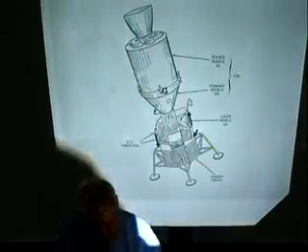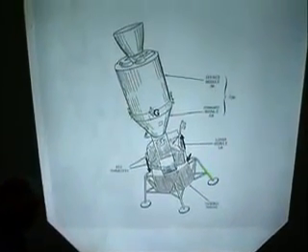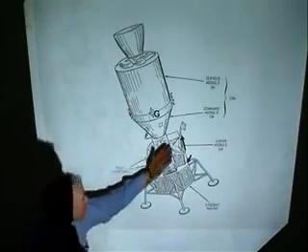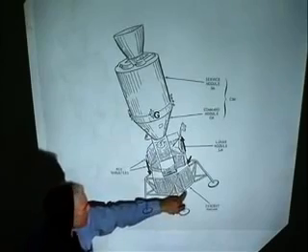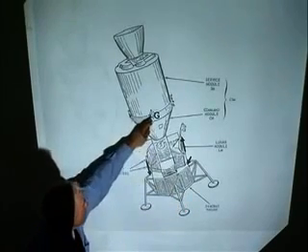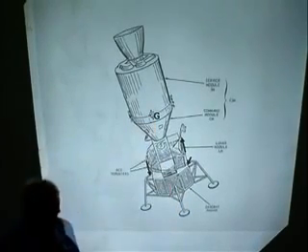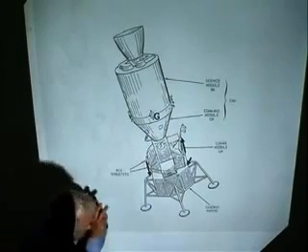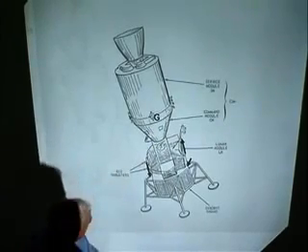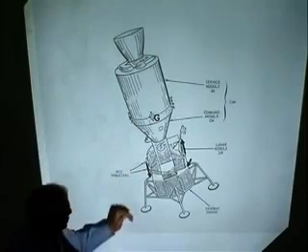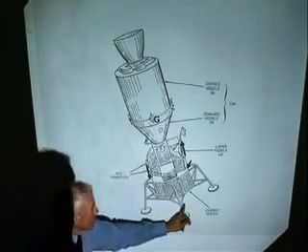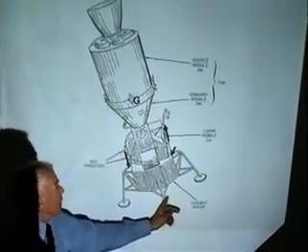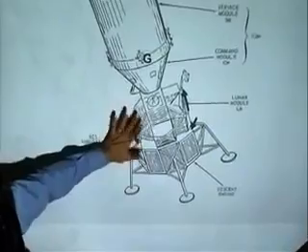Okay, so here's the challenge. With the problems of the impingement of the exhaust and this and that, I wanted to see if there was some way to use this gimbalable main engine, center of gravity way up here, just slowly slewing that back and forth while the main descent engine is firing and pushing this whole configuration, to actually steer it while it's firing, just using this gimbaled descent engine and hopefully not even using any of the attitude control jet's fuel.